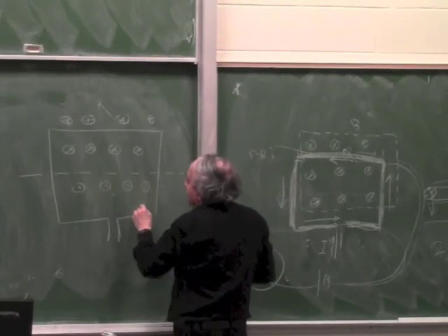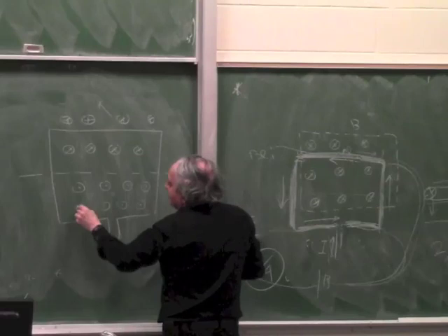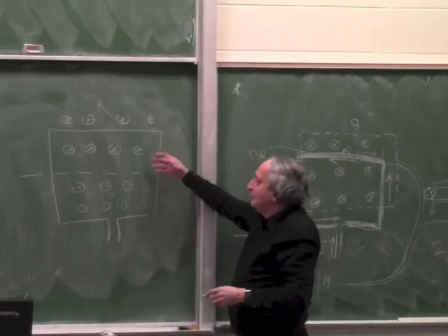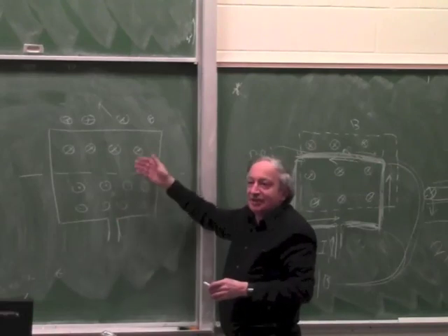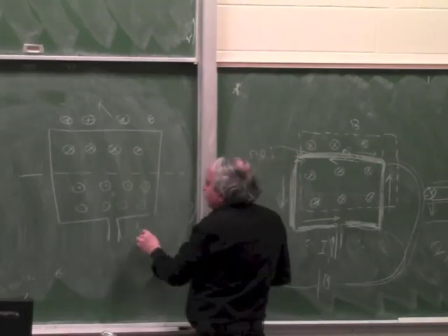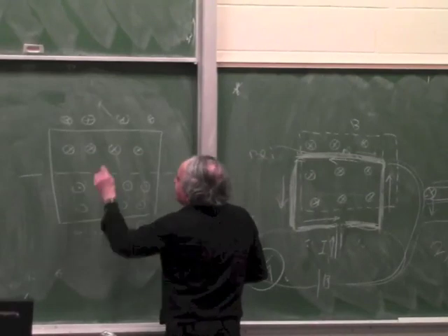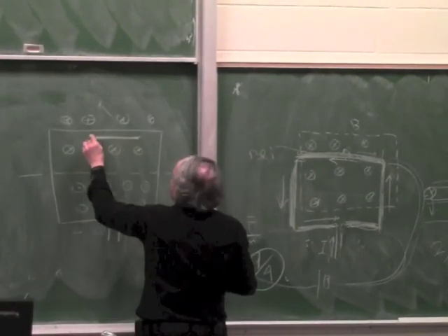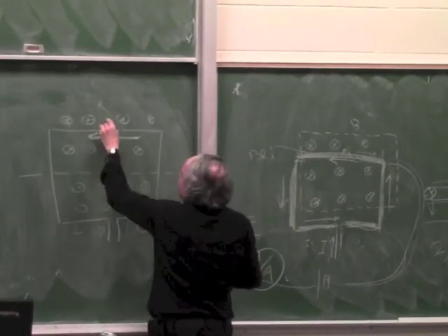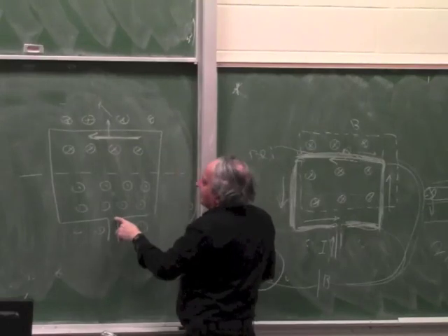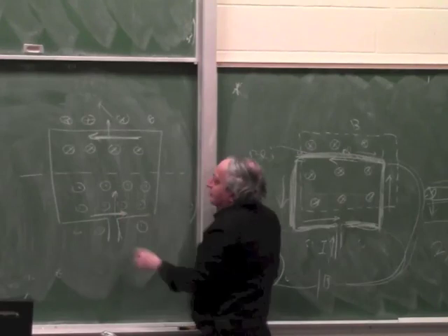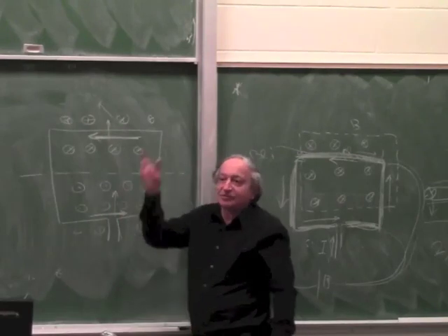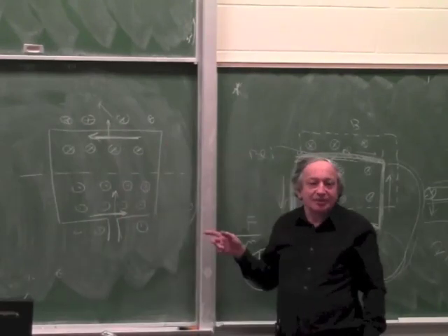Now it's very easy to do that, because these are permanent magnets, but you can make it from 2 magnet pairs and just flip over the magnet. So it's not difficult to make a magnet like this. Now when I do that, this current, if I draw it the same as before, let's say we'll make a force this way. Now this current is reversed, but also the magnetic field is reversed, so the force will reverse, so both forces will add up. Is that clear to everybody?